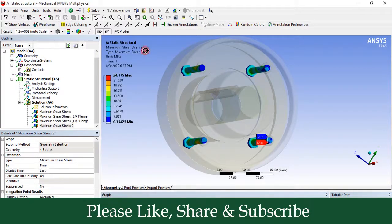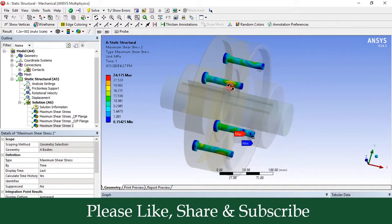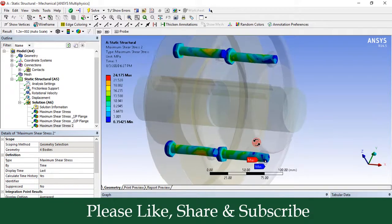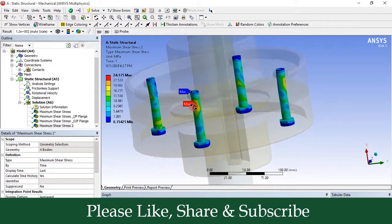So you can see clearly here the stress variation in the bolts. So here the shear stress is maximum at this point of bolt, and it is minimum at this point of bolt. So it is minimum at the free end and it is maximum at this point of bolt.